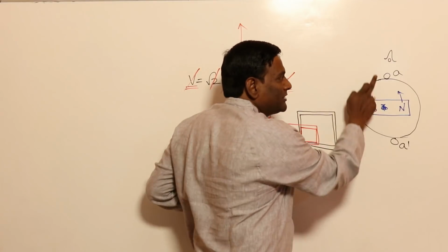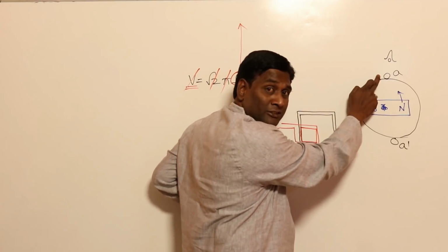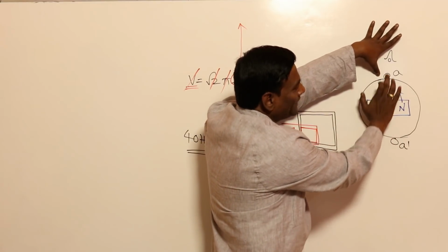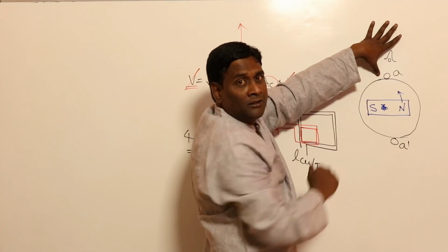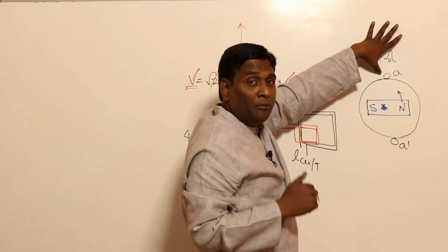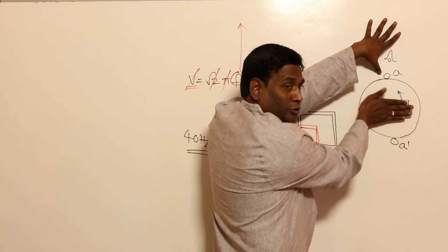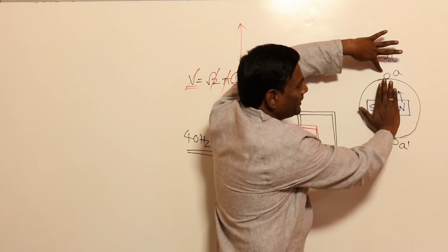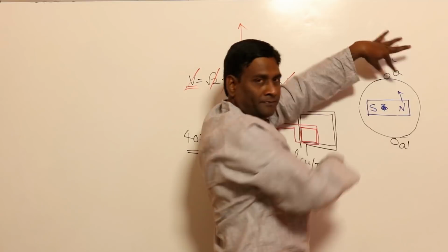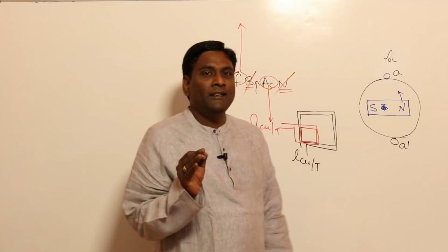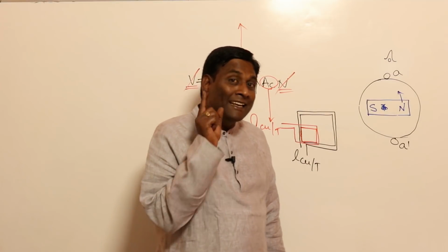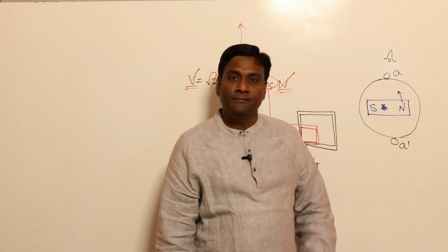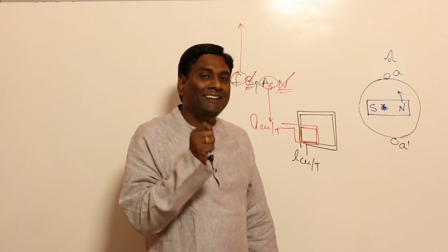As of now, how much is the induced voltage when the pole is here? Zero. After 90 degrees, my conductor will be exactly under the pole center, and the induced voltage will be maximum. So zero here, as of now zero induced voltage, positive maximum, zero, negative maximum, zero. So the logic here is, in order to get one cycle of induced voltage, the rotor has to rotate one revolution, mechanically.